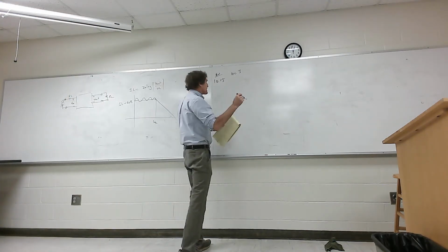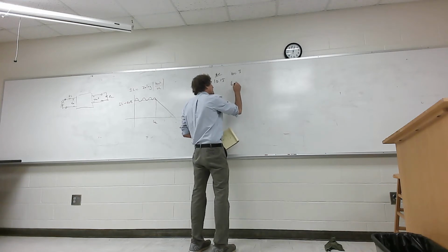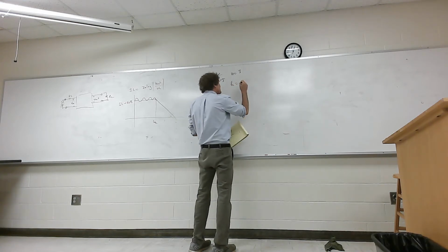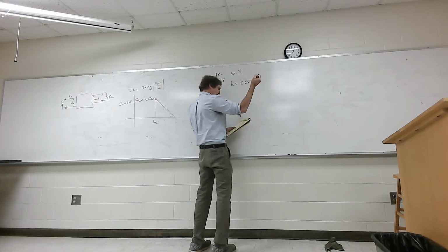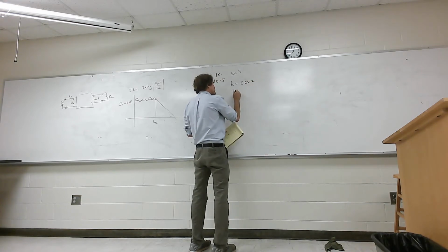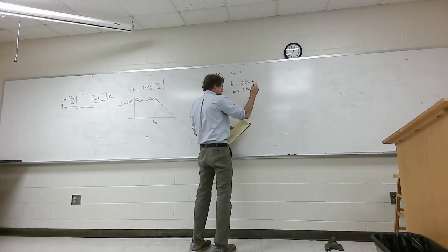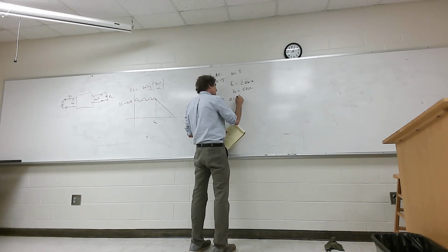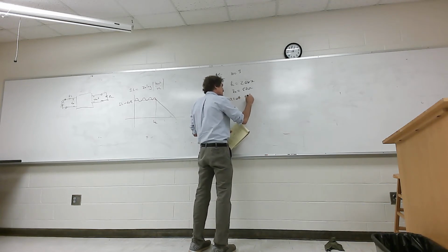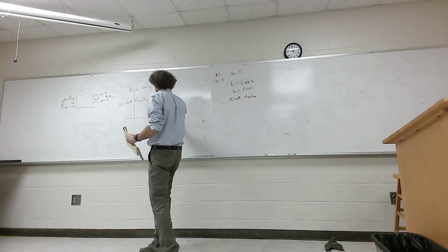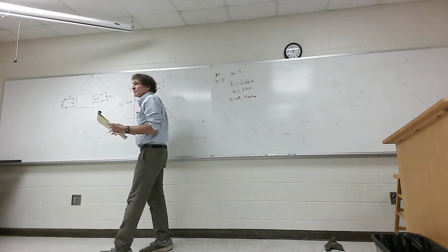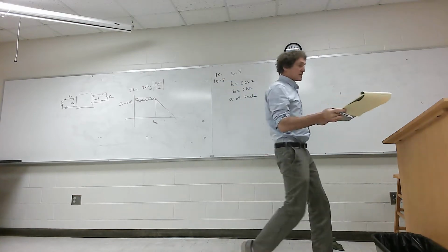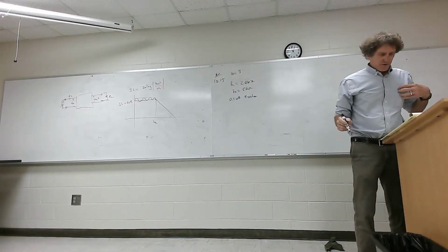So for this one, it's an fc, a cutoff frequency of 2 gigahertz, all right? And has a Z0, a characteristic impedance of 50 ohms, which is about typical for microwave. And they want 0.1 dB of ripple. That's a very small amount of ripple, so it's a fairly flat filter. And these are the requirements.